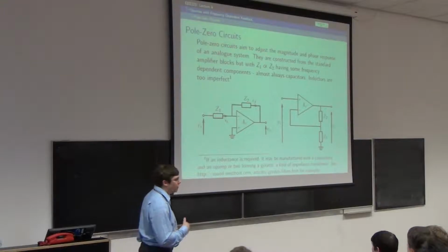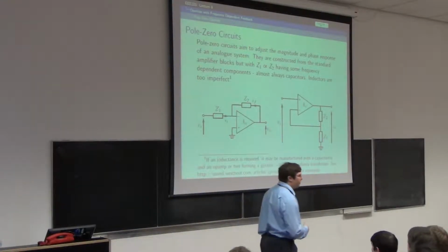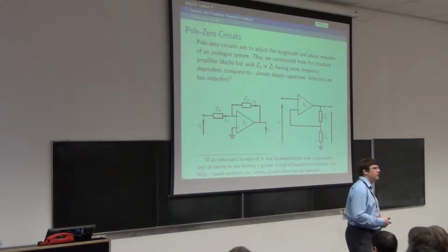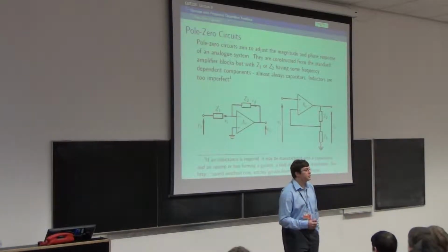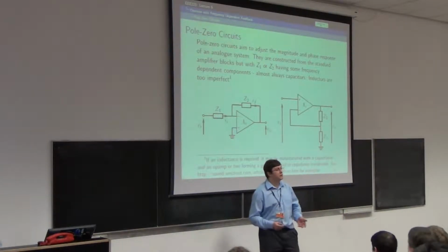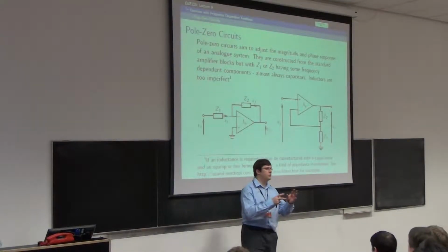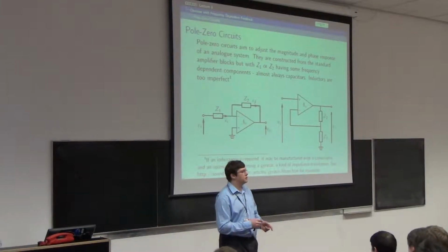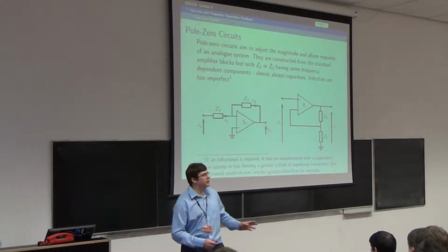They have a lot of winding resistance, especially if you want a decent size, like a big inductance to carry even a small current. You have lots and lots of turns of quite fine wire. You want a fine wire because if you use a fat wire, it takes up a lot more space, and you have to have a bigger piece of magnetic stuff to contain all that fat wire. So you want a thin wire which ups your resistance, which makes your inductor look like L plus R rather than just L. So generally speaking, you chuck out inductors.